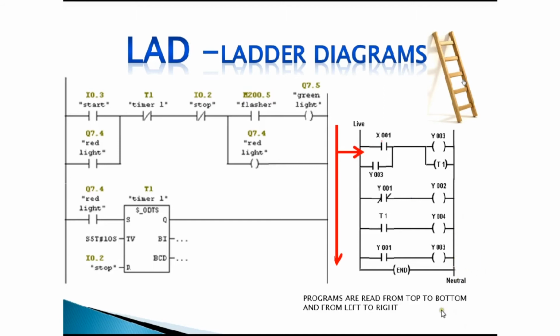If there are, then it will look at what it does: it's going to energize contact 003. It will then send the required signal to the output module to make the changes, for example, turn the motor on. And as I said, it will continue going through the program from top to bottom, observing all the changes, and then making the necessary adjustments to your output modules.